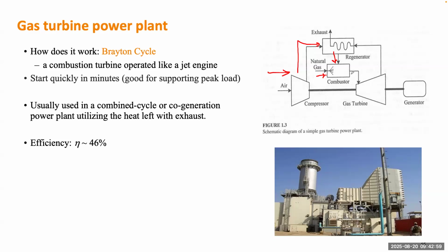So you may wonder, the operating temperature of a gas turbine can be much higher than the steam turbine generator, but why is the efficiency still the same? The reason is, when you increase the temperature of the compressed air inside of this gas turbine generator, the temperature of the air leaving the engine is also very high. Because to increase efficiency, you need to make the inside temperature very high and the outside temperature very low. Then you can have a high efficiency.